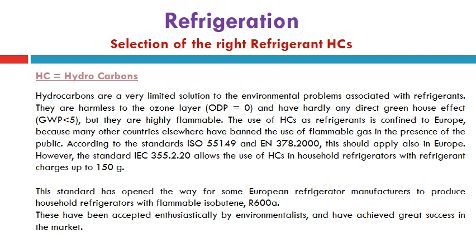Hydrocarbons. The hydrocarbons are a very limited solution to the environmental problem associated with refrigerants. They are harmless to the ozone layer, ODP equals 0, and have hardly any direct greenhouse effect with GWP less than 5, but they are highly flammable.